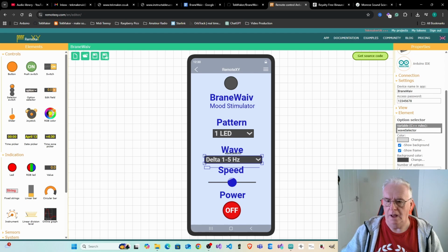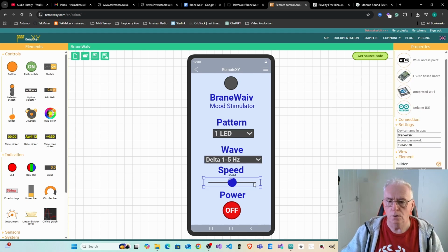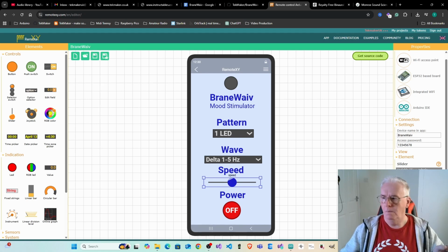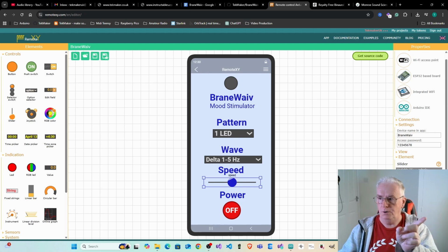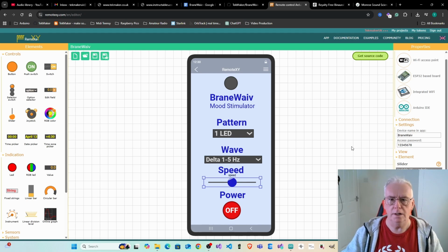I've just put a little thing in to guide you as to which one is which in terms of frequency, and then you can refer to my document. And the power control returns a variable I call speed, and that goes from -100, I'm pointing but you can't see my hand, -100 to 0, +100, and then I've done a little calculation to scale it.